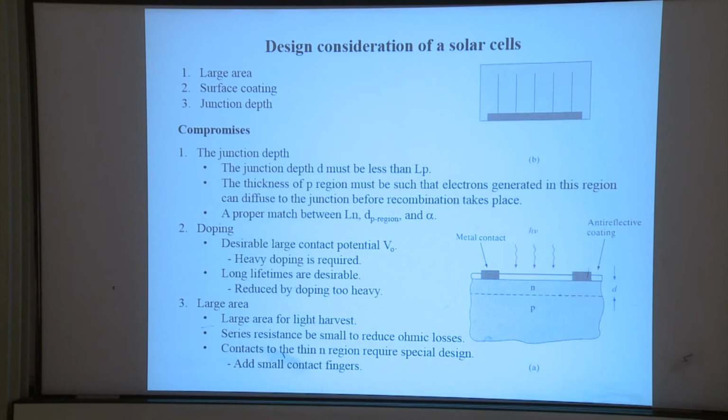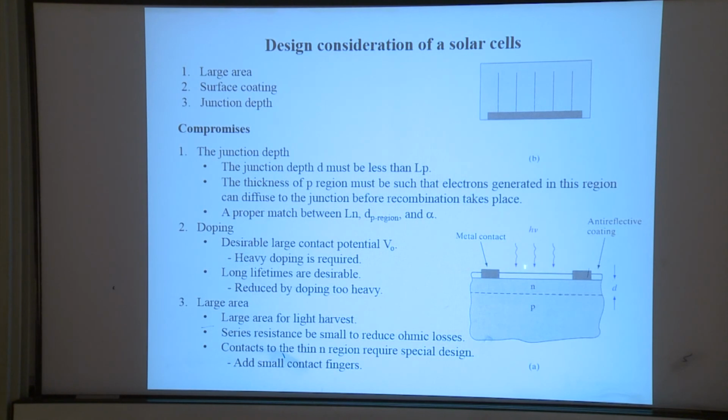When the dopant of N-type exceeds the dopant of P-type, it becomes N-type. They counterbalance each other, and if you put more heavily doped N over the previously doped P, then you will convert the top one to N-type.